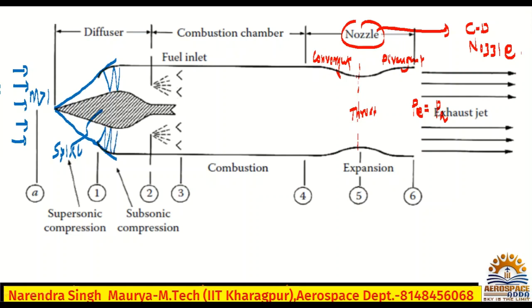So basically, in general, I will tell you, because this is the sharp edge, we'll get an oblique shock, and in an oblique shock the flow will slow down, but Mach will be greater than 1, meaning still supersonic flow, but yes, flow will slow down in an oblique shock. But once a normal shock is formed here, after multiple oblique shocks, after the normal shock the flow will be 100% subsonic. So here you can say this flow has now become subsonic. This is the subsonic flow.